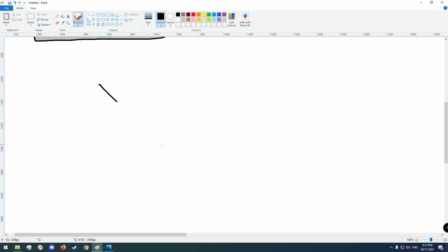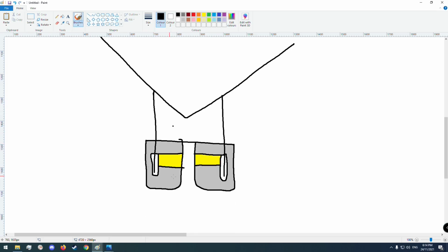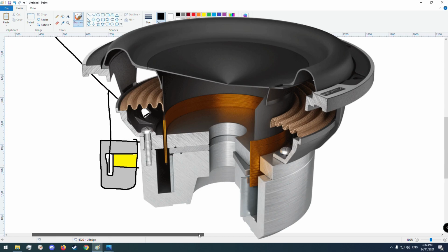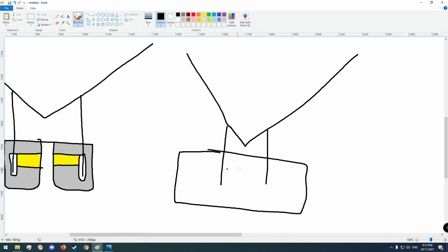In fact, what you can do with some speakers is, if you imagine this is the cone here, if you put a wide voice coil on it, you can get the magnet to be so small that the entire magnet fits inside the voice coil of the speaker, instead of standard scenarios which need a giant magnet outside the speaker with the pole vent right there.